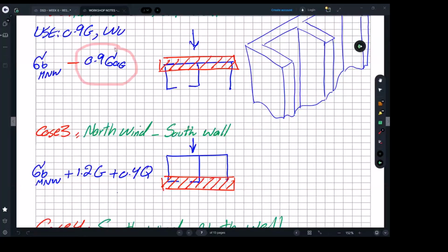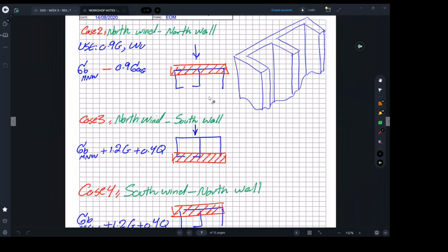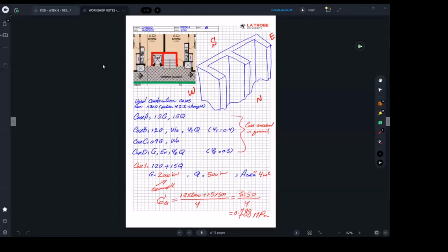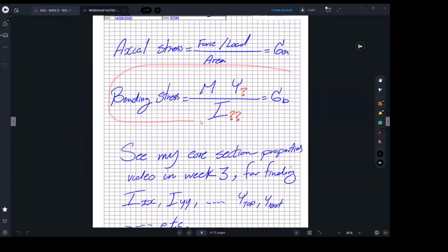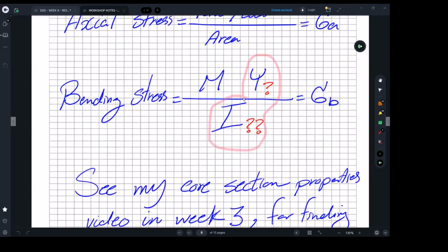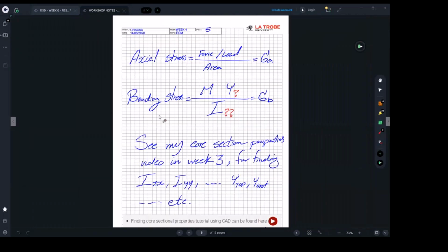And because we have dead load, which the student was asking me about, 90% of that dead load can actually help to push things down, right? And that's why, but these stresses, they are axial stresses. Right, stop me if you need a question. So what I was saying, for these bending stresses, we should use this formula. Now you can see bending stress is a function of properties I asked you to pre-calculate, and it is a function of the moment value at whatever level we want to assess the core at. And that's really what I'm showing you here.